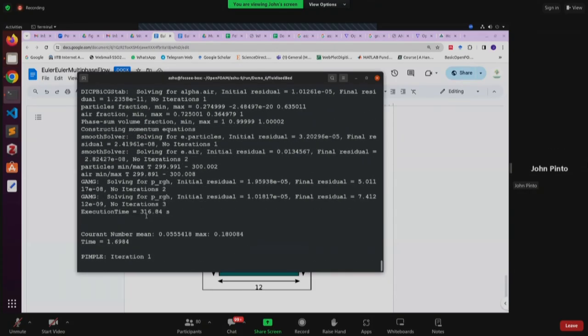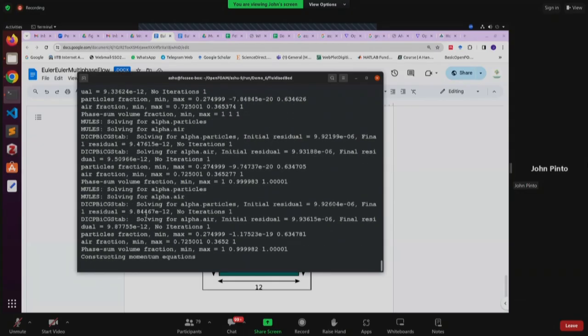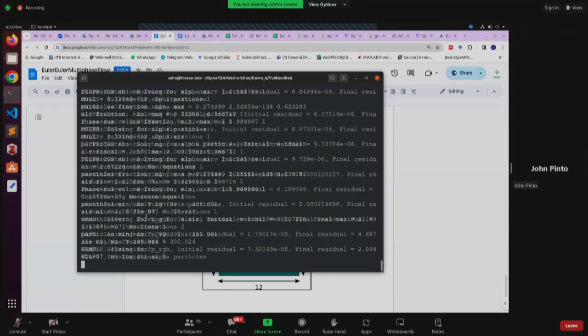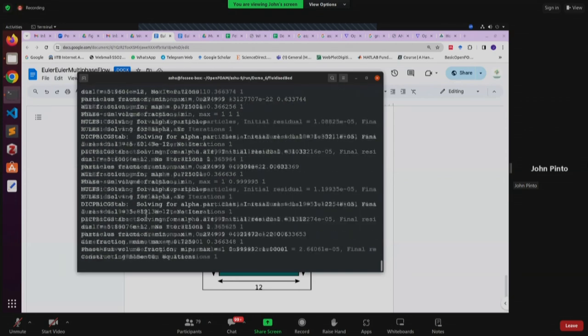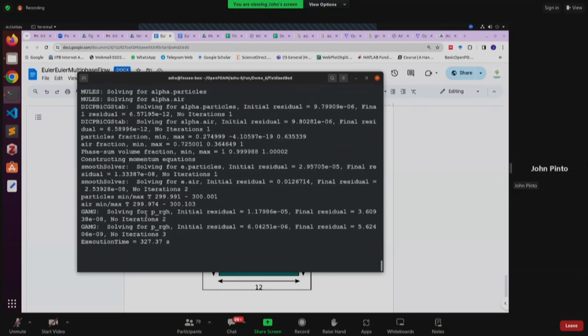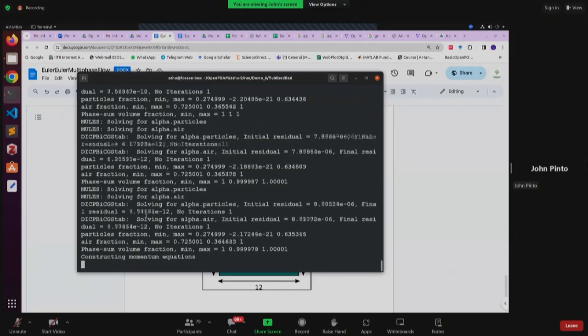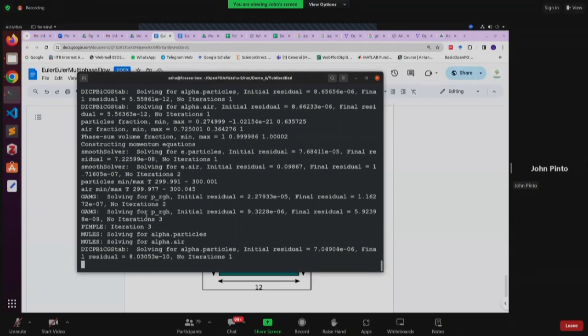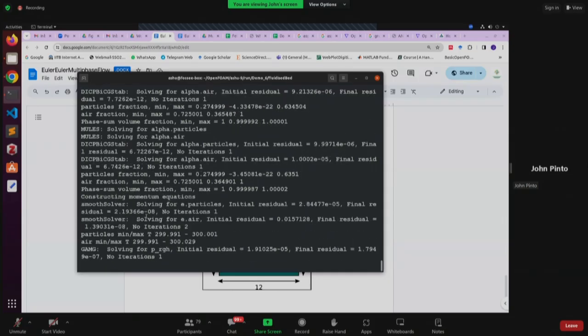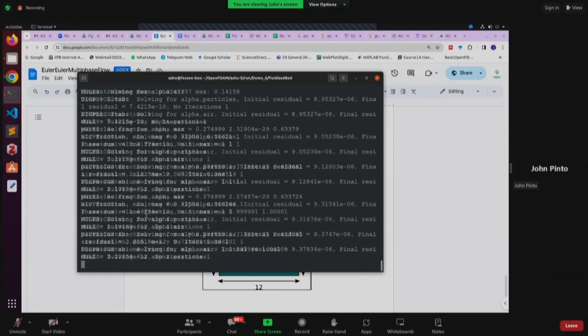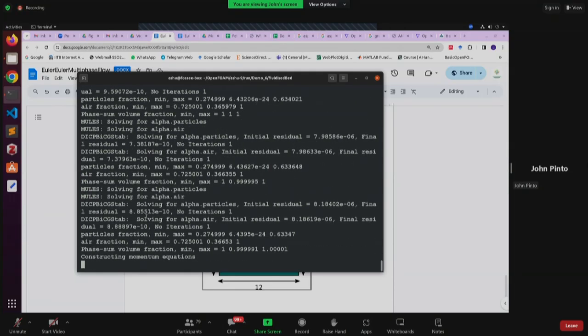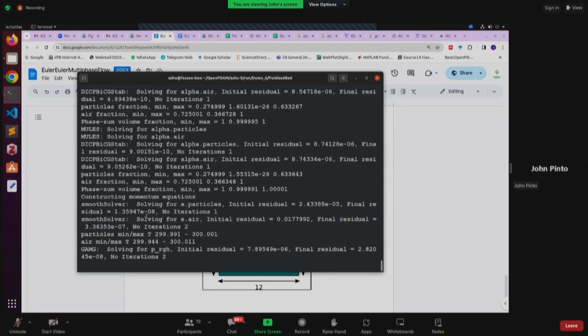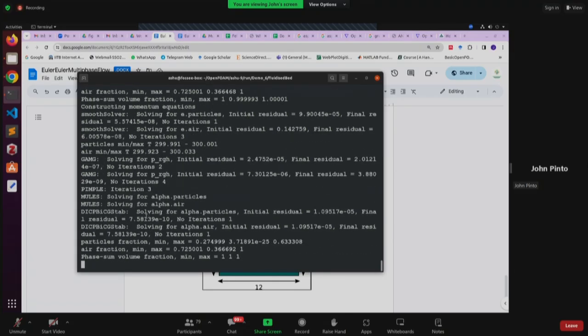Okay. For that, we have a tutorial. Is it available in OpenFOAM? Let me check. I don't remember whether we have it on our website or not. But what you can do is select a wedge type of geometry. You can think of it like cutting a birthday cake: you cut a wedge. For a 2D approximation, the wedge angle will be very small, close to 5 degrees if I remember correctly.